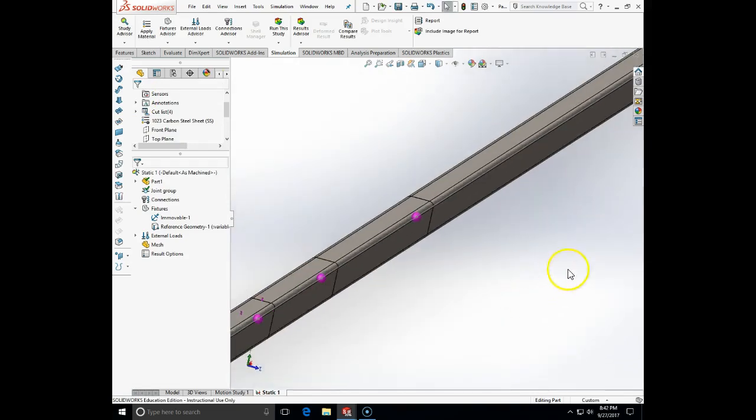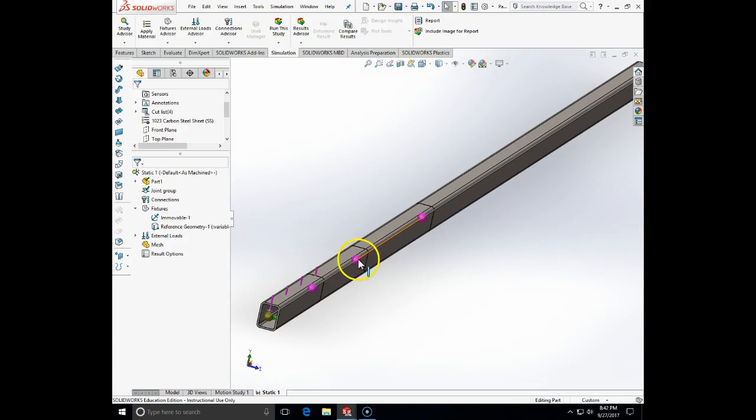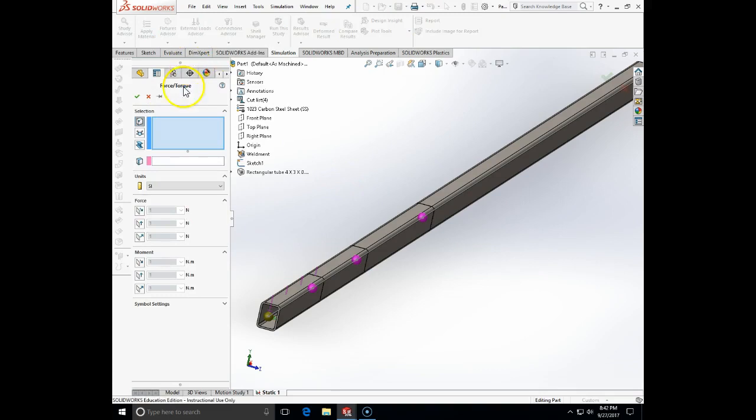Now my second load is a point load acting in this node. And that point load is vertical downwards 5 kips, 5,000 pounds. So I'm going again external advisor force, again the English, but this time instead of using the beam, I will use the joint or a node. I will click on the node.